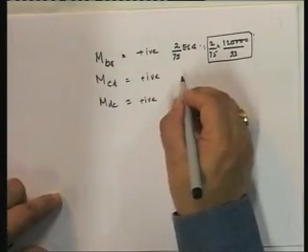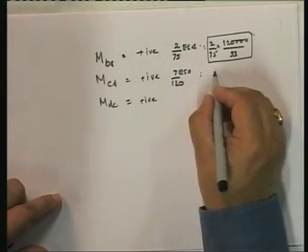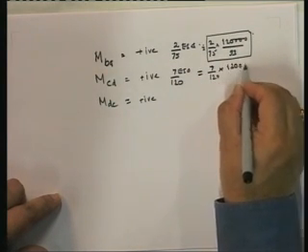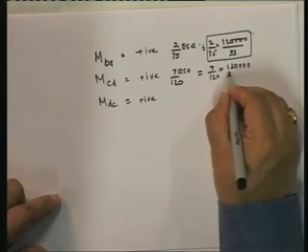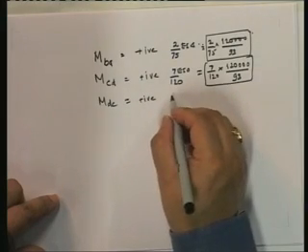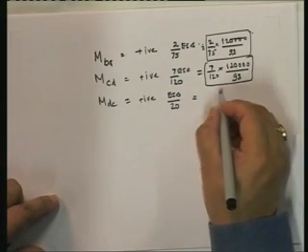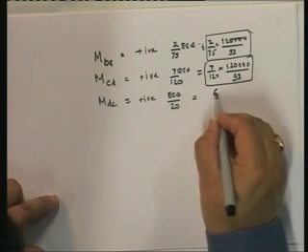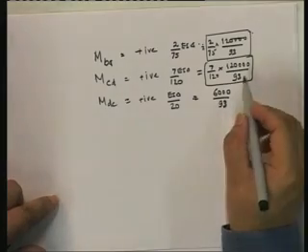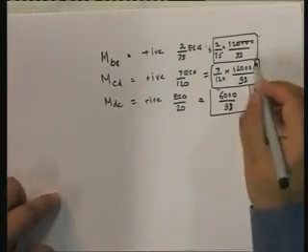MCD is equal to 7 EI upon 120. So this is going to be equal to 7 upon 120 into divided by 93. And MDC, which is equal to EI delta upon 20, is going to be equal to, 20 goes into this thing, so it's going to be 6,000 upon 93. Okay, so these are the values. Unfortunately I do not have a calculator, but you should be able to obtain these values.